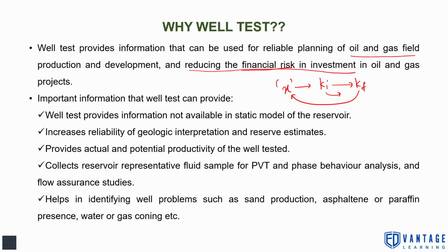So important information that well test can provide is the information that is not available in the static model. As I've told you, it increases reliability of geological interpretation and reserve estimates, provides actual and potential productivity of the well tested, collects representative fluid samples of the reservoir for PVT and phase behavior analysis, and of course flow assurance studies, where we can also understand where the wax deposition happens in the pipeline or on the tubing, where condensate banking is happening if it is a gas condensate reservoir. We can also help in identifying well problems such as sand production, asphaltene or paraffin presence, water or gas coning, etc.